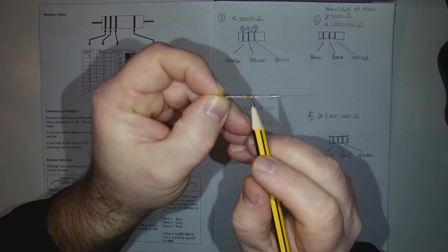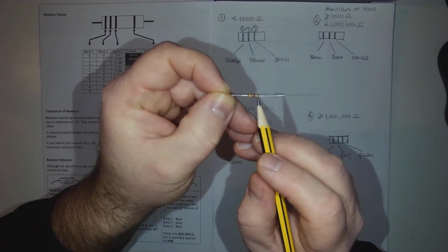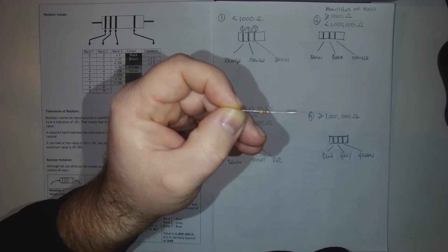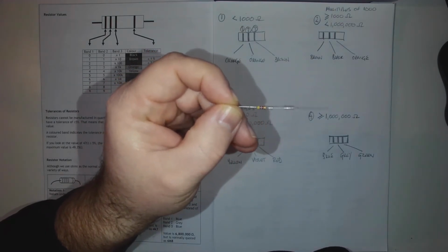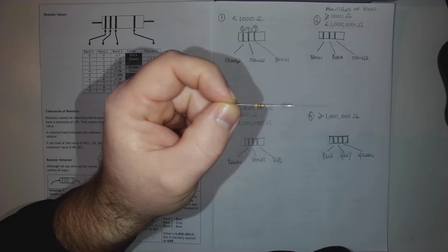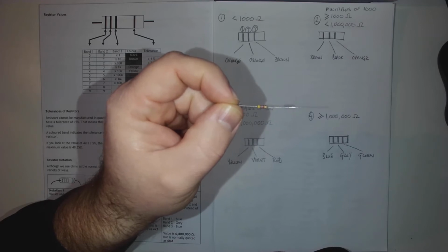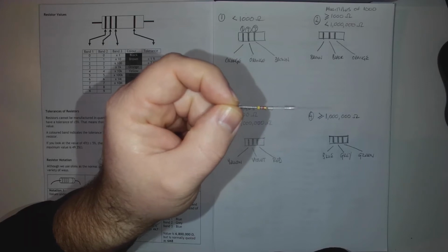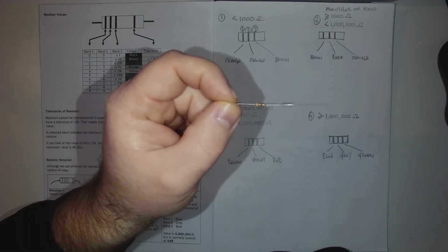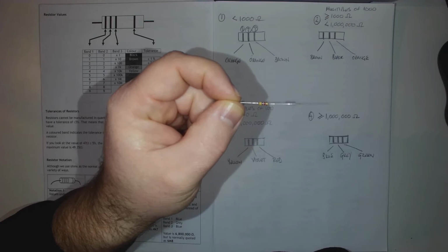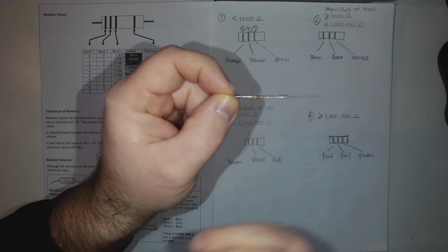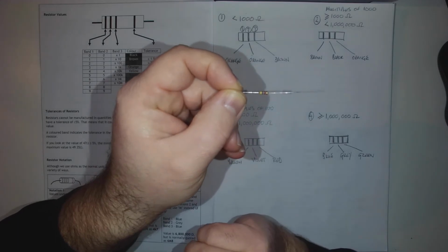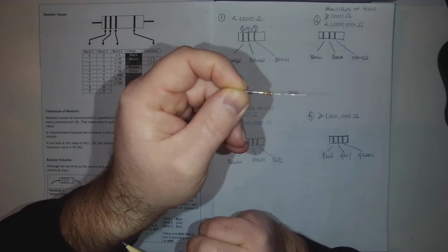The last colour band in this one is gold, which is in relation to the tolerance of the resistor value, and that essentially means how much bigger or smaller the resistor value might actually be compared to what it was intended to be, and that's there because it's very, very difficult and expensive to manufacture resistors of an absolutely precise value. However, for what we're doing, we don't need to worry about that 4th colour band, but the first 3 colour bands we are interested in using to decipher.